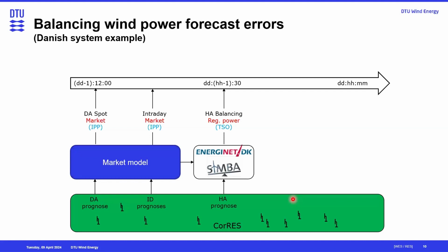They now see what has been bid in the market and what my 1 hour ahead prognosis of the renewables forecast is, and I can calculate my imbalance, and then instead of a market, I have a list, a merit order. I know which is the cheapest generator with this capability, which can provide my power within 1 hour.